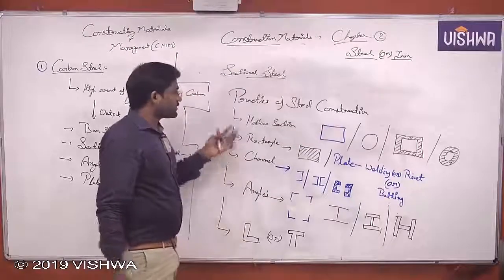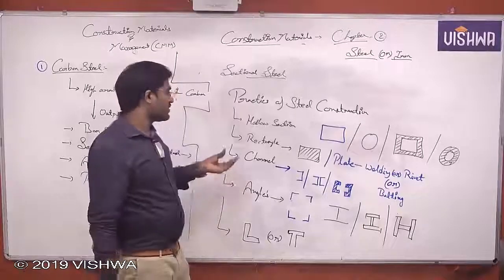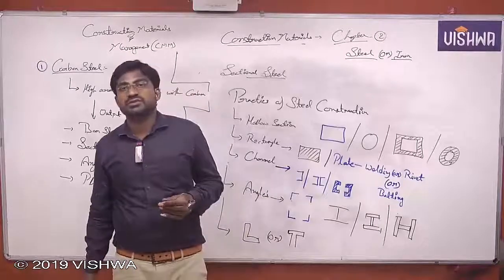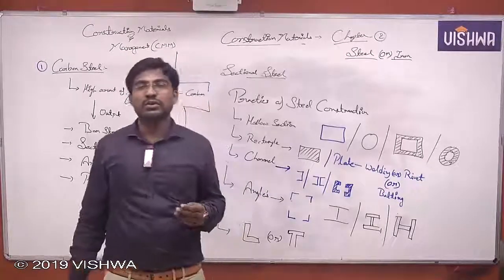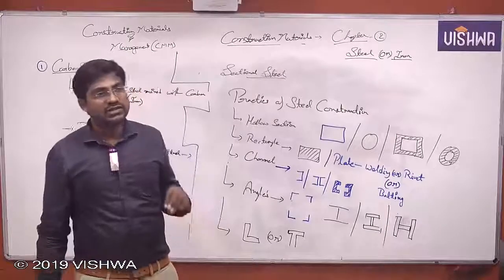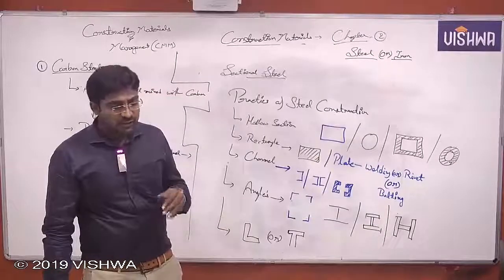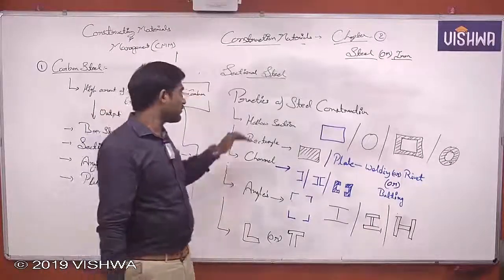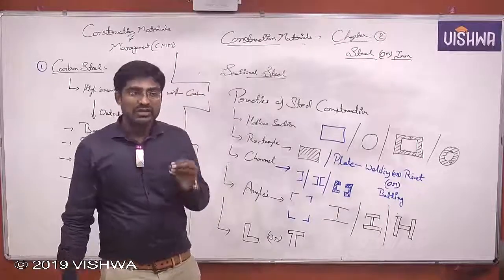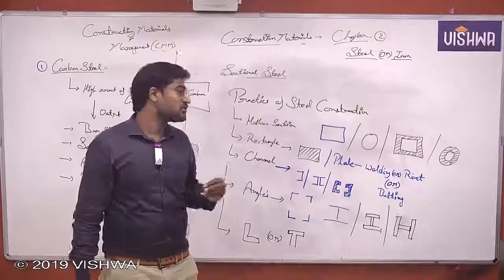What type of sectional steel is available? If you are going with the individual one, the hollow sections, we can see them in all constructions where the load is generally lesser. In general practice, we adopt them for saving material. If we are going by economical aspects, we allocate hollow sections, which are mostly preferable. As per the load, we can arrange either with respect to circumference or with respect to the area.